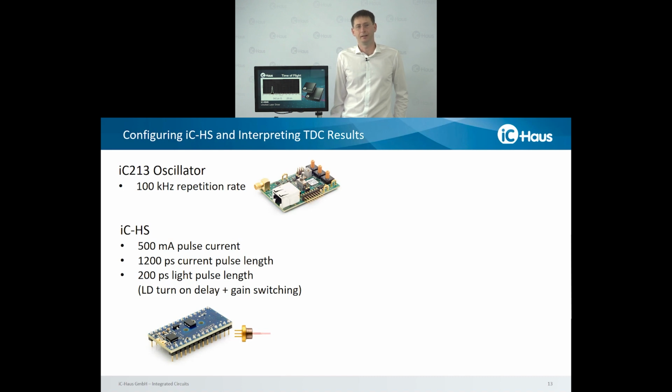Pulse length should be easily visible on our oscilloscope screen, so that you as an audience can easily read it, but more important, it should be as short as possible so that we can make use of the gain switching effect and, if you build your design around the SPAD, have less ambiguity on this.